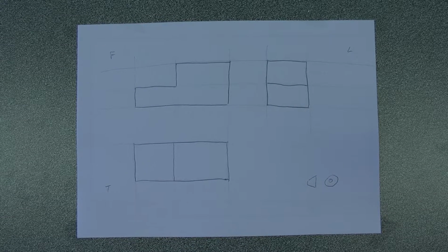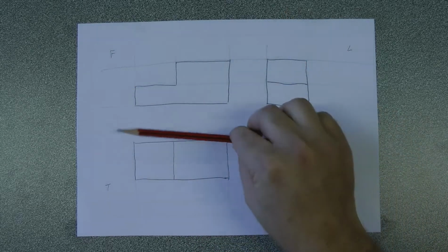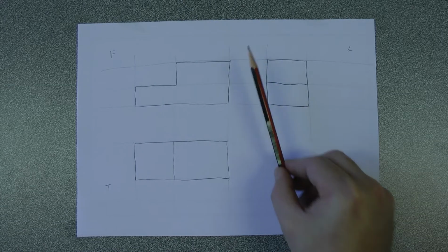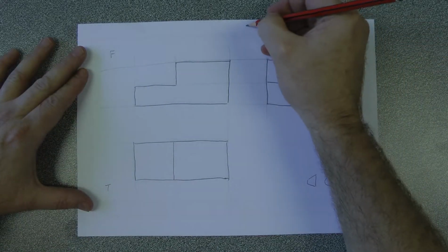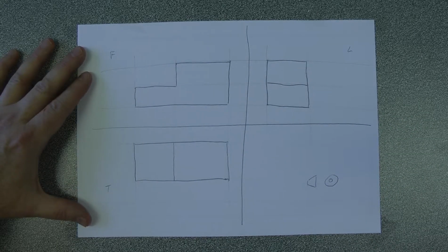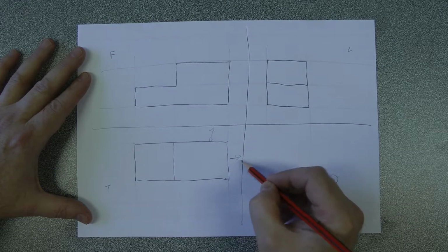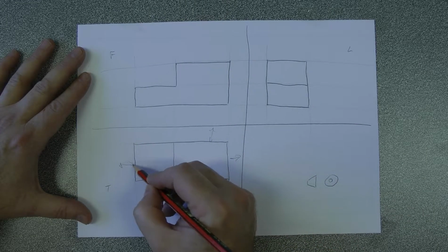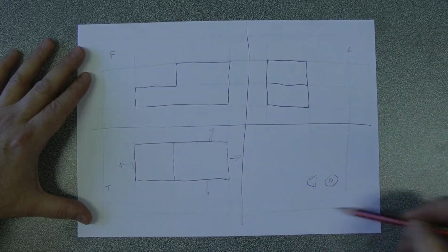And you'll see that I've laid it out in this way. This is the way we're going to be doing it, with a front, a top, a left, and some space in between. So when you come to your drawing paper underneath here, what we're going to do is again lay it out. We need to do some spacing. So on this drawing paper, I'm actually going to put two dividing lines. I'm going to put a vertical one down here and a horizontal one across there. And I'm going to have to make sure that I've got a bit of space around the shape all the way, just so that it fits inside the border of the drawing paper.